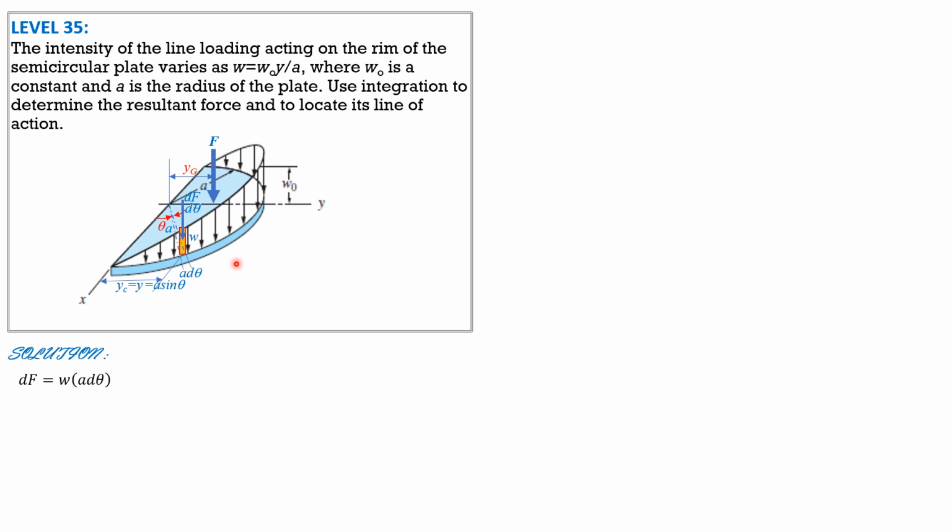So differential force is W times A d theta. Substitute dF equals W, it's W0 Y over A times A d theta. Cancel out A. So dF is W0 times the integral of y d theta, where y is A sine theta from the figure. So integral of y, which is A sine theta d theta. Since A is constant, so F is W0 A.